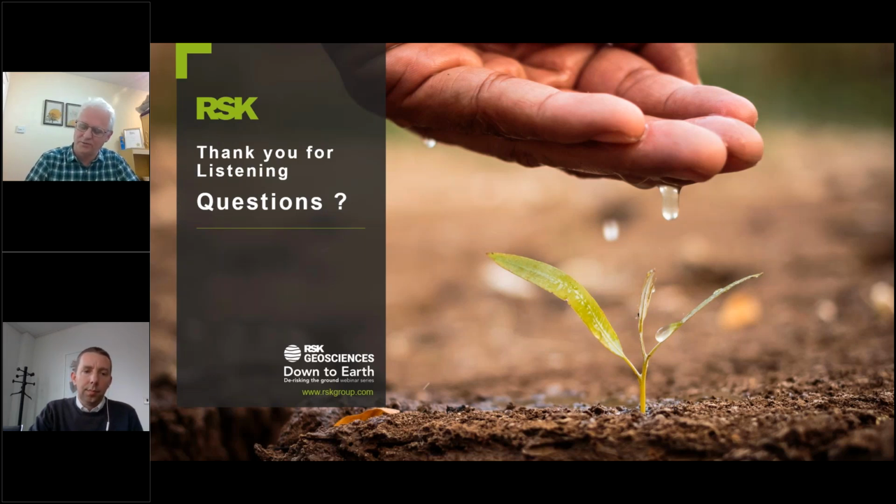You would also have that ability to do the moisture content depth profiling near to the tree. It's a bit like, how do we get these standards in the first place? A lot of this work goes back to research in the late 1990s, where people were looking at an existing tree and taking moisture profiles a lateral distance away and at different depths, almost producing a moisture contour map, and then you can look at zones of influence.